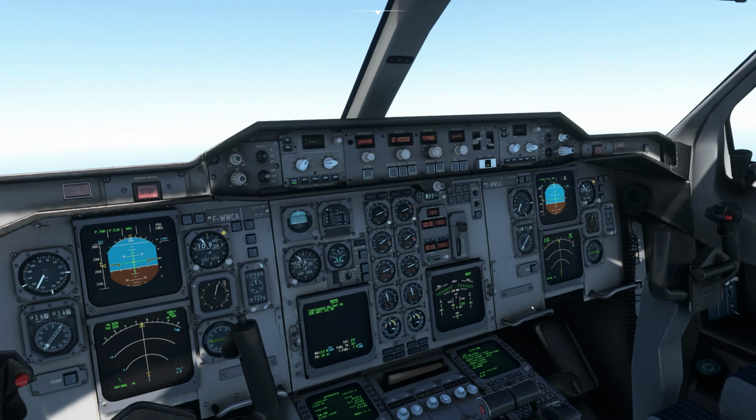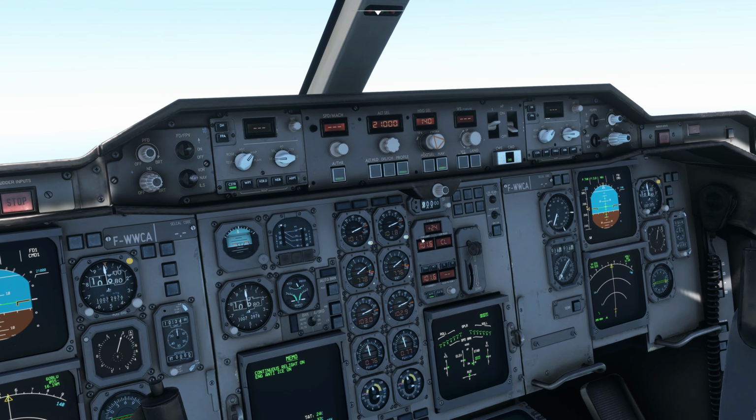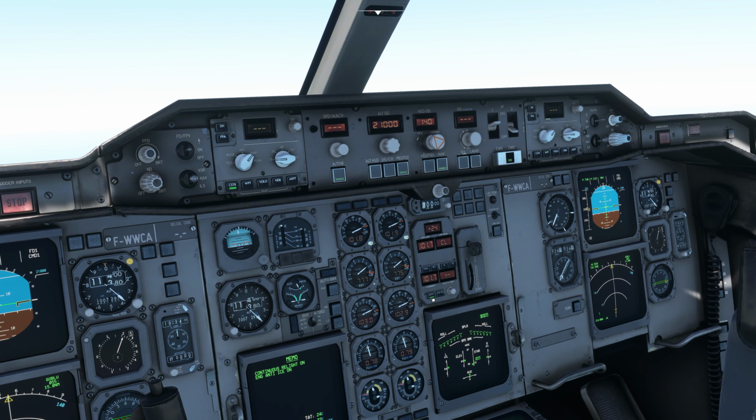I would just like to tell you one more thing. If you look at this panel, you will see different modes that the thrust is in. Right now it's in the climb mode, and the thrust limit is also coming, and you can see it's set to auto. You can always change the thrust settings. You can either climb, cruise, MCT, or TOGA.